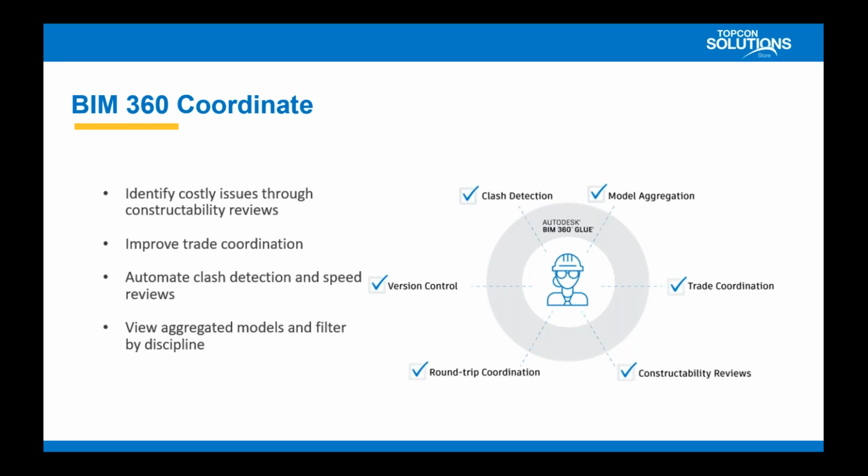But another thing I wanted to talk about here is you're going to notice that it says Autodesk BIM 360 Glue. Well, that's kind of where this Coordinate came from, right? And if you guys will remember, we used to be able to create those shared views and publish those with our team as well. You can do that with Coordinate, okay? So we're going to be able to, of course, see those clashes, save that view if we want to, and send that off. And remember, if we create an issue within BIM 360, now that we have that issue engine tied together with Navisworks and with Revit, if we have these coordination issues, these clashes, you can take that issue, again, connect it right back into your design program, and it shows you exactly where this is.